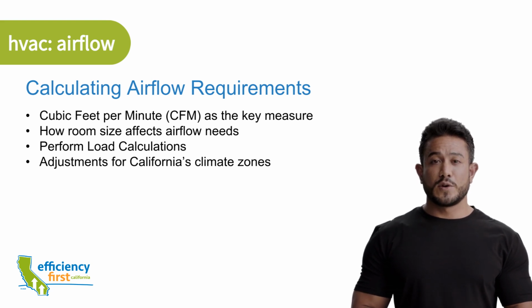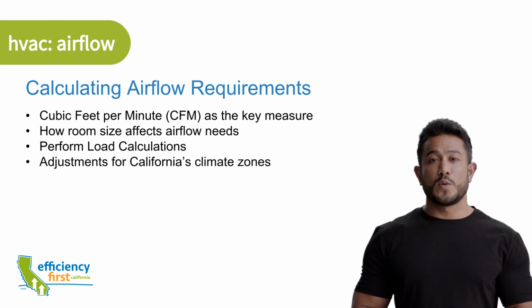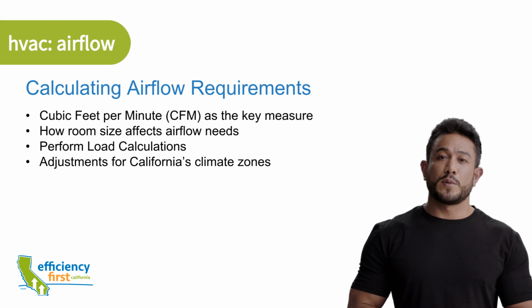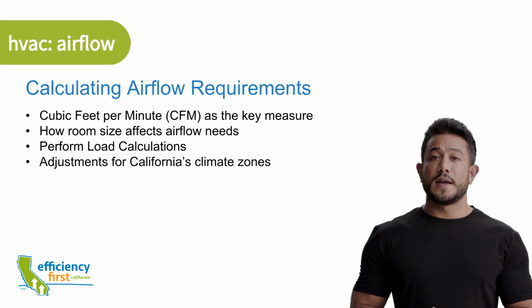Calculating the right airflow for each room is important to ensure consistent temperature and air quality. The larger the room, the more airflow it requires. To calculate airflow for each room, load calculations should be performed. This ensures that each room gets the proper amount of air given its orientation, fenestration, insulation levels, and exposure to